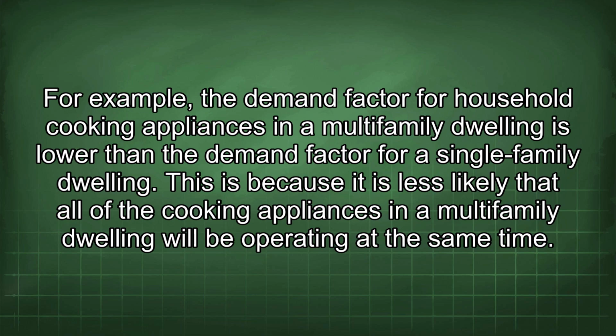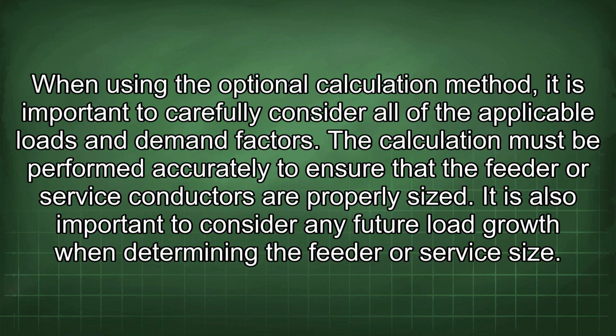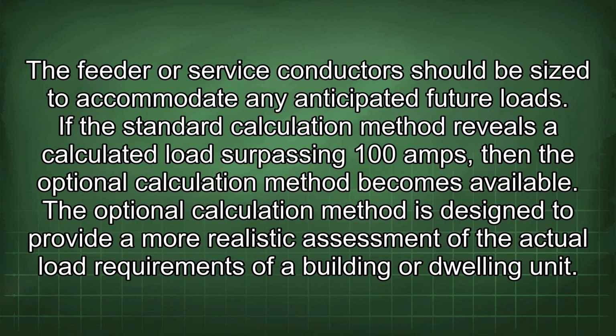This is because it is less likely that all of the cooking appliances in a multifamily dwelling will be operating at the same time. When using the optional calculation method, it is important to carefully consider all of the applicable loads and demand factors. The calculation must be performed accurately to ensure that the feeder or service conductors are properly sized. It is also important to consider any future load growth when determining the feeder or service size. A feeder or service conductor should be sized to accommodate any anticipated future loads.